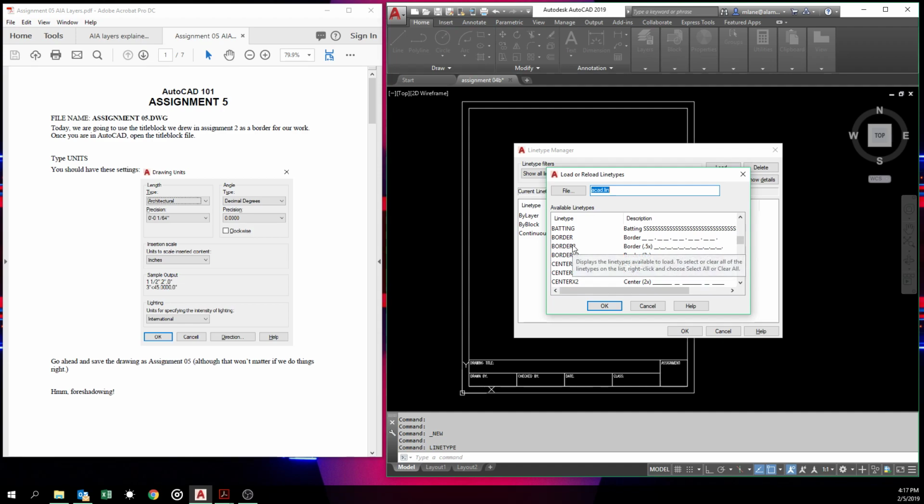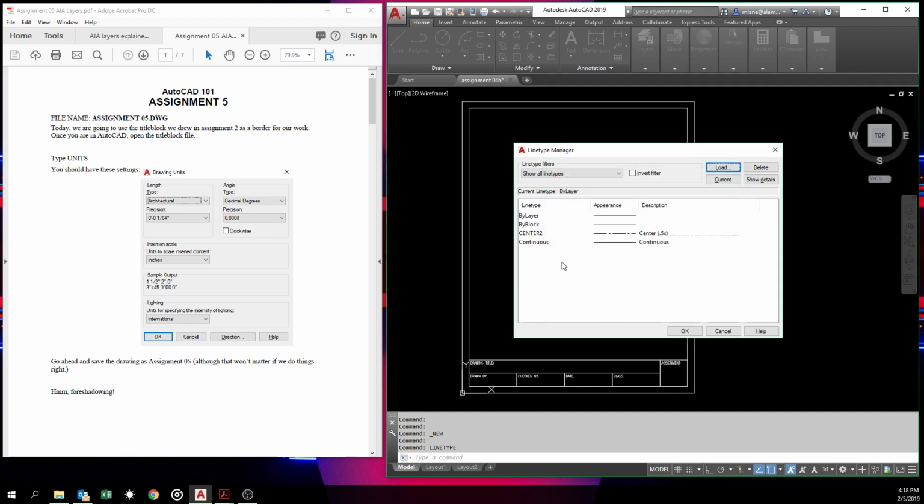Today we're going to load center 2, which is twice as big as center 1, but center 2, dashed 2, and where's hidden 2? Hidden 2. I guess they're half as big as the normal hidden. Hidden X2 would be 2 times as big. But we're going to get those. But you'll notice if we pick on center 2, pick, and I hit OK, well, it's here.